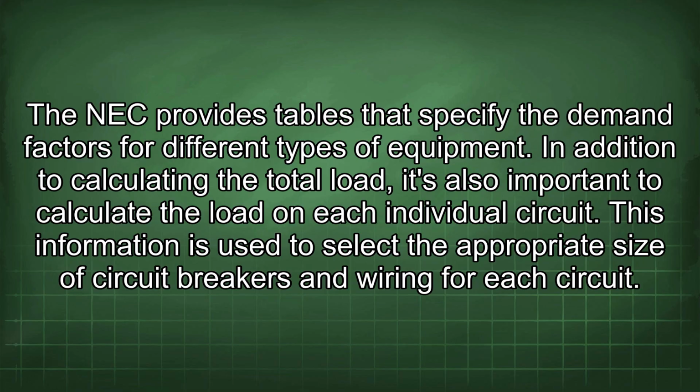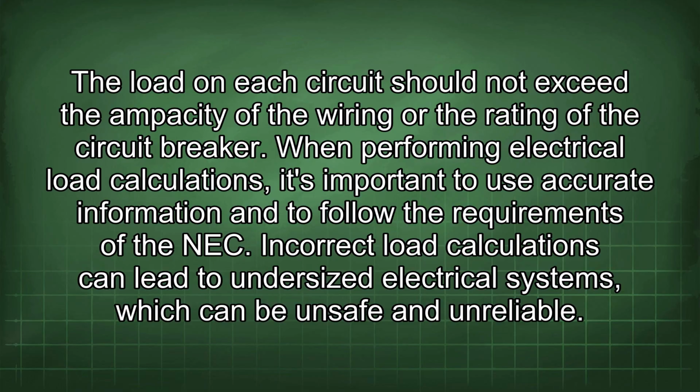In addition to calculating the total load, it's also important to calculate the load on each individual circuit. This information is used to select the appropriate size of circuit breakers and wiring for each circuit. The load on each circuit should not exceed the ampacity of the wiring or the rating of the circuit breaker. When performing electrical load calculations, it's important to use accurate information and to follow the requirements of the NEC.